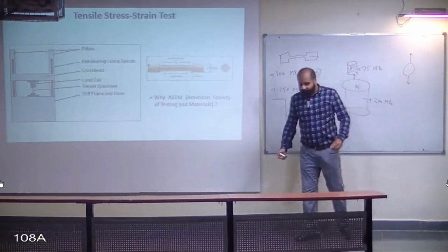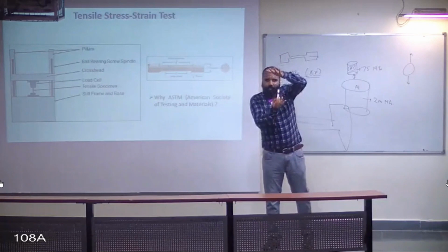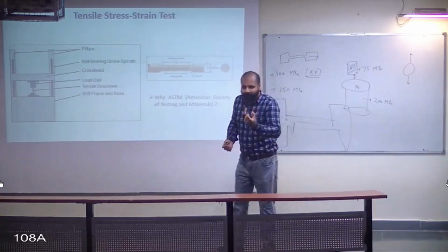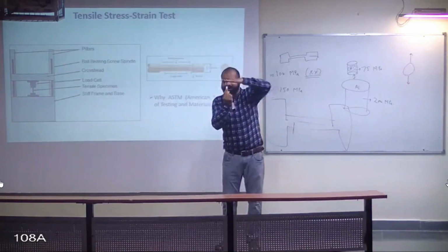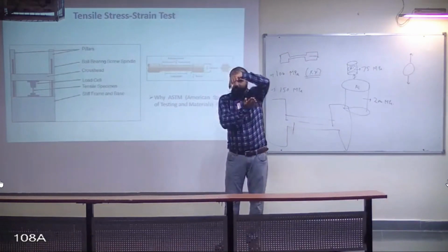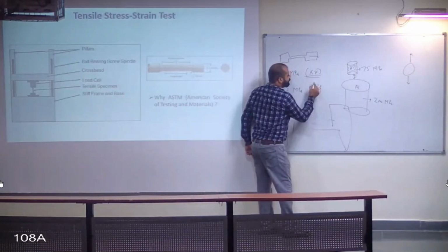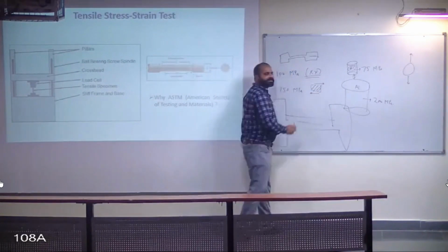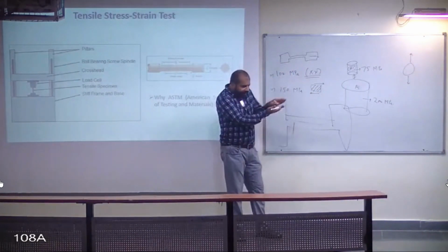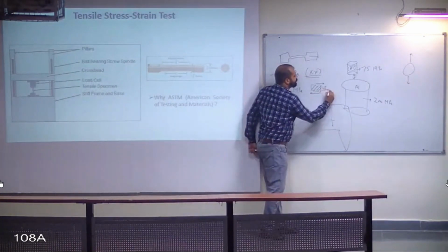it is tensile. If you are pressing it, it is compressive. And if you rub it like this from the top and rub from the bottom like this, I repeat, suppose this is your sample, if I am applying a stress in this direction and from the bottom I am applying stress in this direction, then this is your shear component, shear stress.